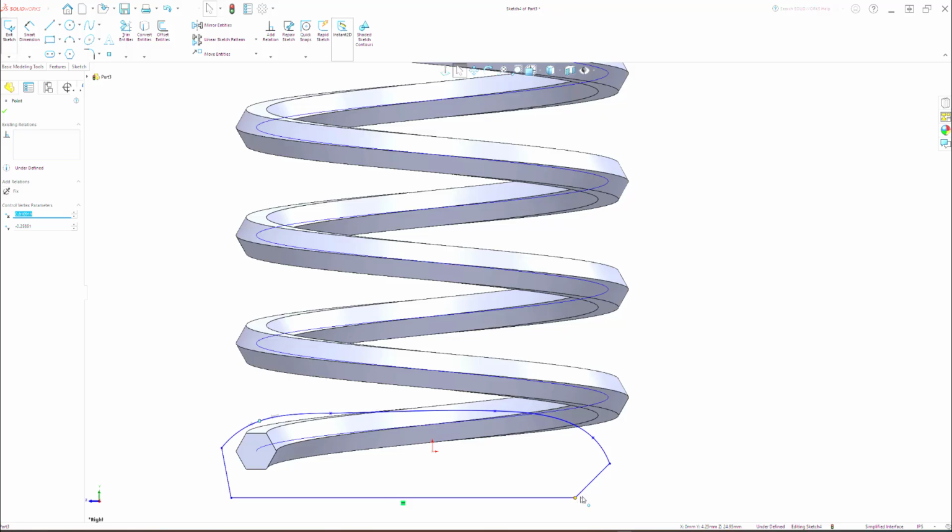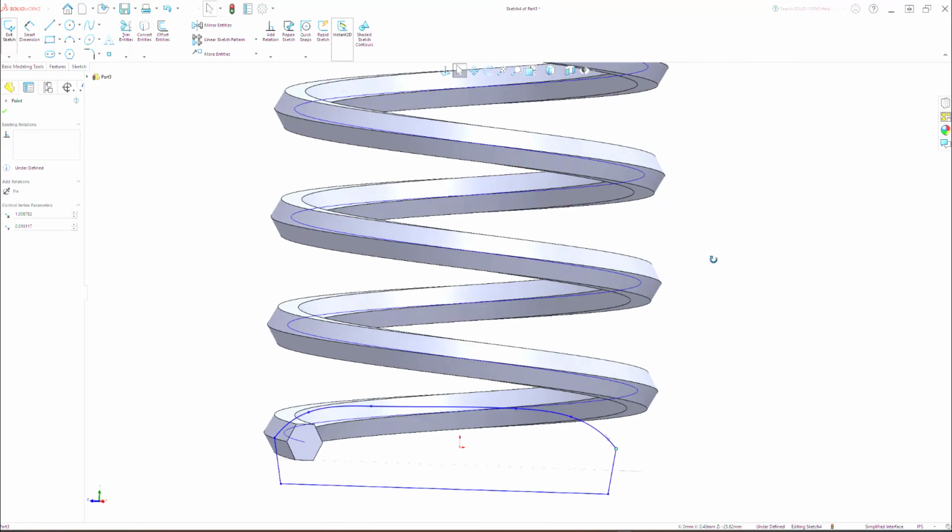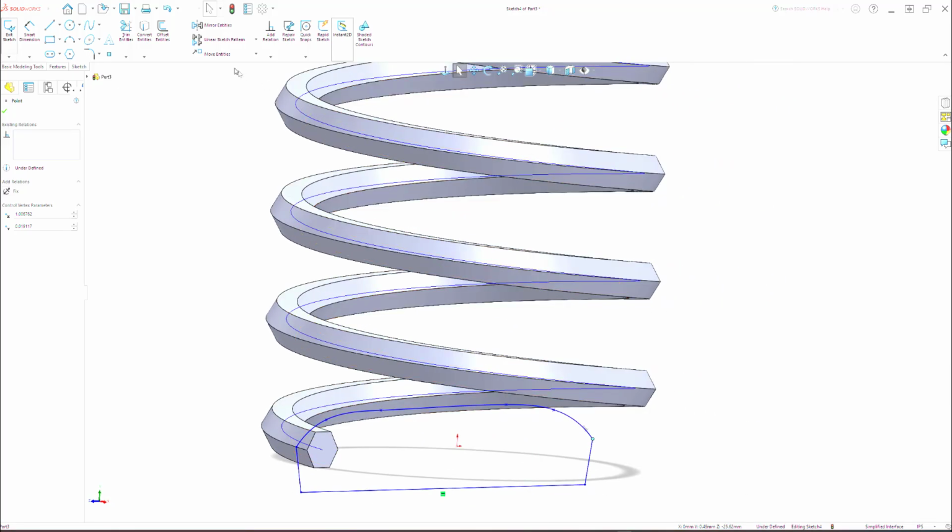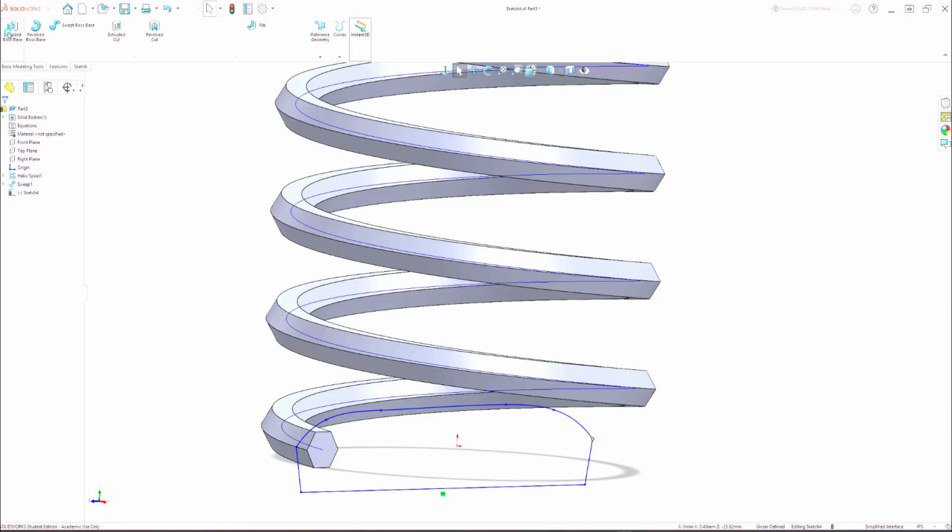And again, the ends, you can adjust these, and that's the idea, is that you can adjust these ends and positions. So that way, the coil acts and reacts and looks pretty similarly. And you can use data points, like for example, you can see now that these are level. All right, so we've got this end kind of well shaped here. We'll choose OK and go into Features, Extruded Boss Base.